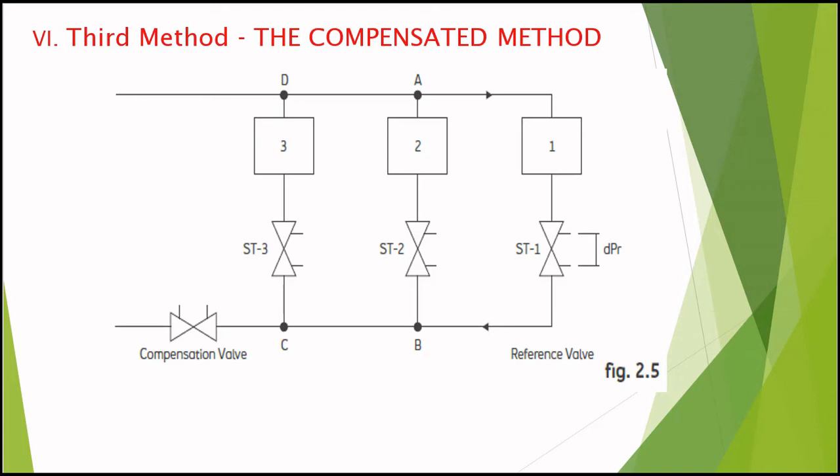Normally, in hydronic balancing, when we change the flow rate through the balancing valve, the pressure drop of that circuit is changed, and consequently, since the hydronic circuits are connected to each other, those of all branches will also be changed.